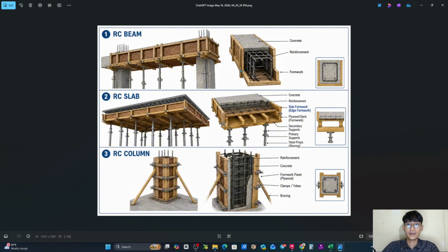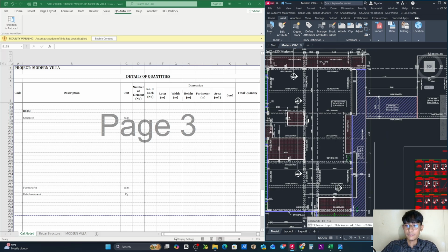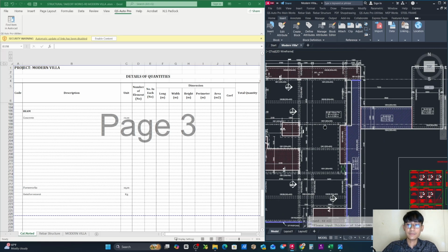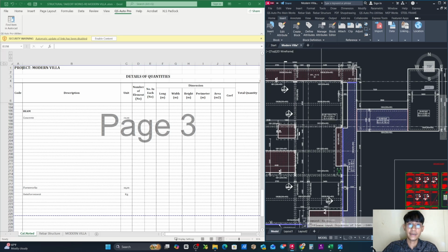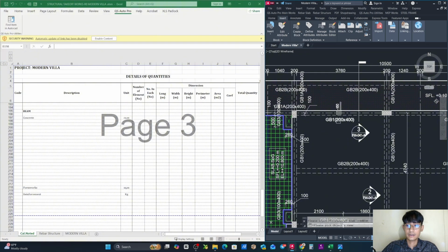It is exactly what happens at the side. Basically, the beam and the slab overlap. So if you want the accurate quantity, you need to input the thickness of the slab. So when it's duplicated, it will cut 100 millimeter thickness automatically. But in the case right now, I just keep it 0. We take the full height of the beam. So you type 0 and enter.